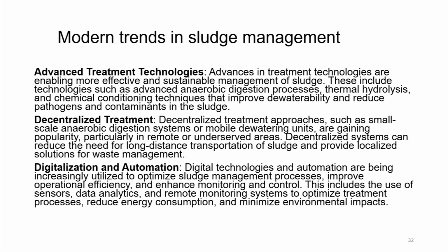Advanced treatment technologies. Advances in treatment technologies are enabling more effective and sustainable management of sludge treatment. These include technologies such as advanced anaerobic digestion processes, thermal hydrolysis and chemical conditioning techniques that improve dewaterability and reduce pathogens and contaminants in sludge.